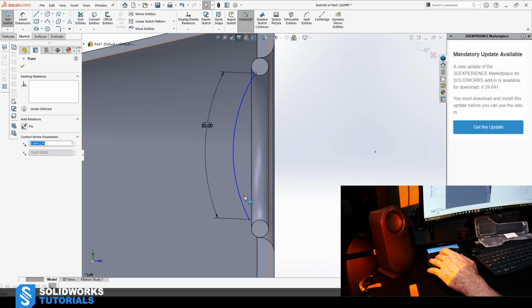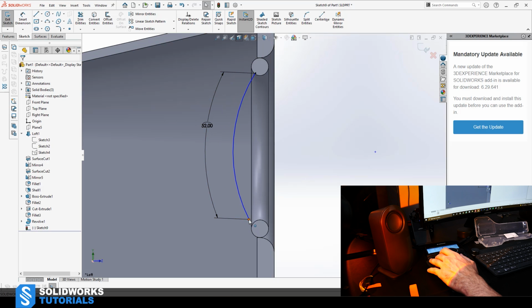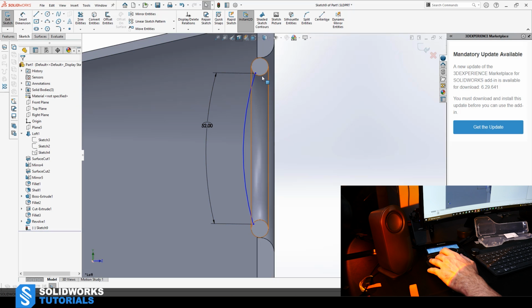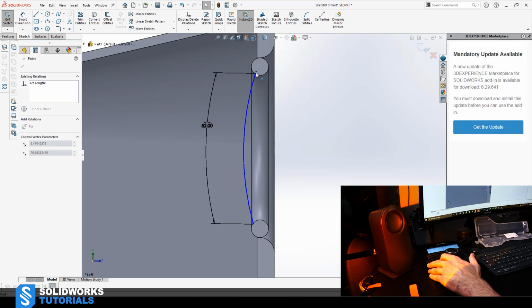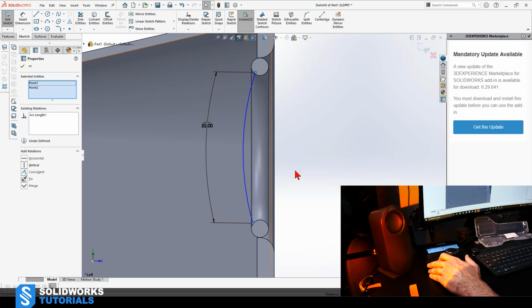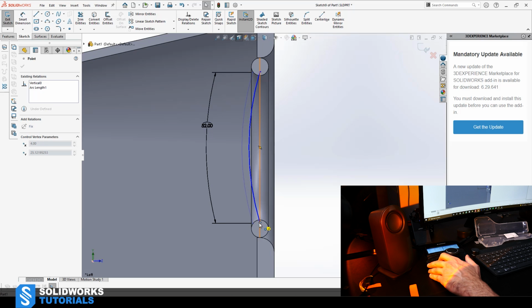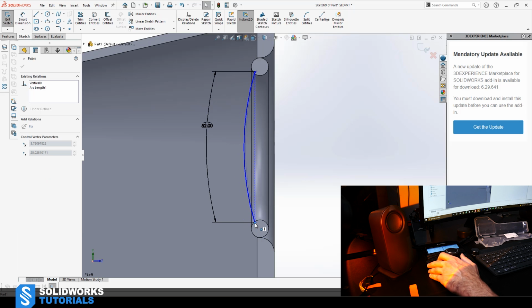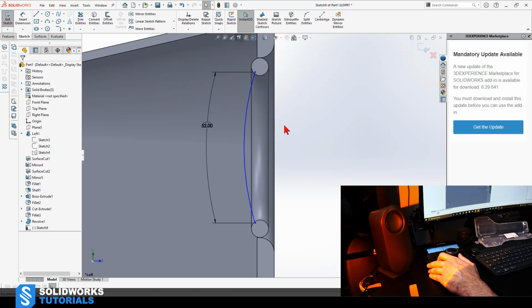okay, let's fix this point. Move this. Oh yeah, look at that. It's definitely good enough. And let's unfix this and move it here. Actually, let's make these 2 points by selecting them both while holding the control key down in a vertical relation. Very good. And place it here. I want both points to be inside the cross section of my ring, which is this one and this one. So as long as the points are inside, I don't really care. Good. Now I have that. Let's fix one of them so it wouldn't move.